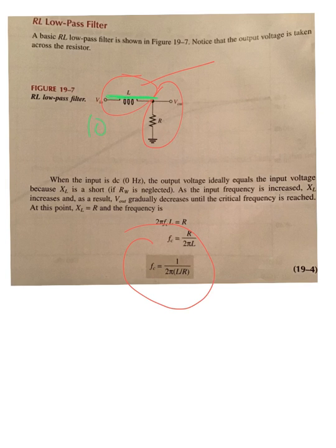So if I put 10 volts in, I get 10 volts out. I put 20 volts in, I get 20 volts out. See how that works? Now, as the frequency rises, the inductor chokes and starts to develop voltage across it, and steals from the output. And that's where you start to get the roll-off at minus 20 dBs per decade.